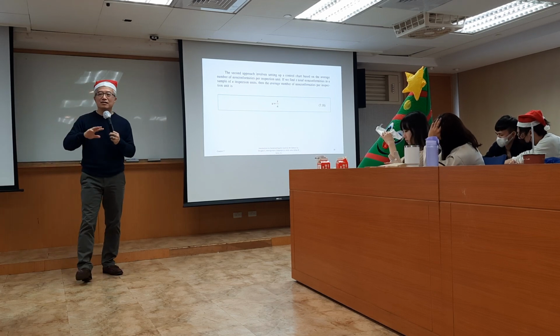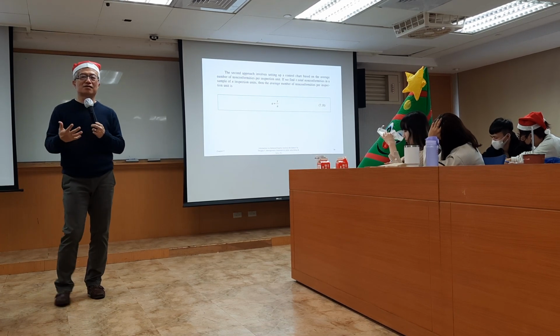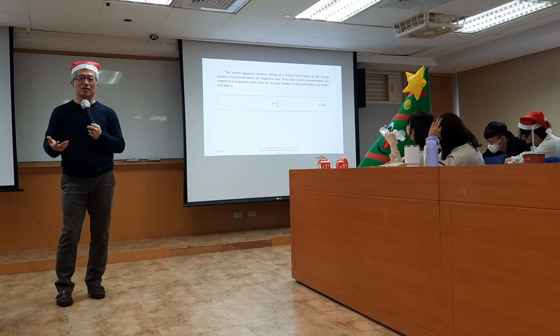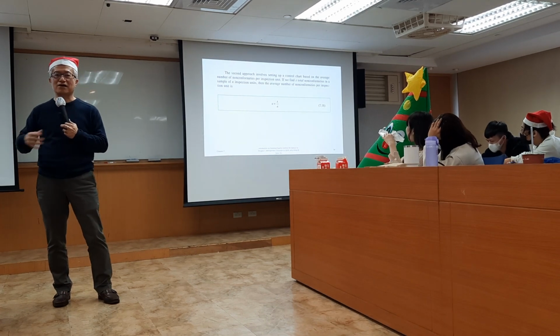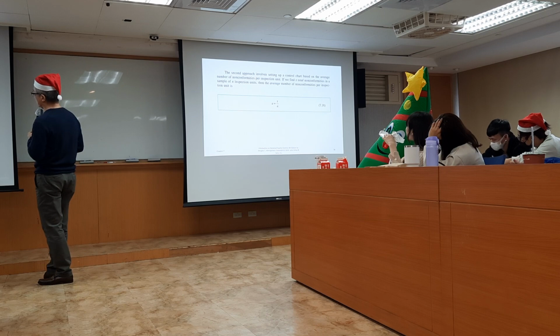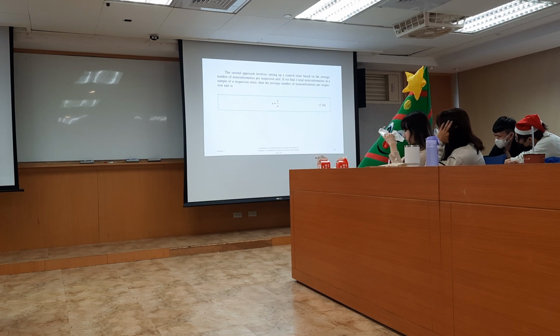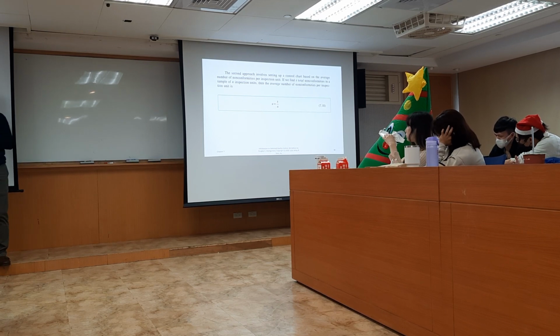And then we find X, the total non-conformities, divided by n inspection units. Sometimes n varies from time to time. This time we will take a sample of size 3. Next time we take a sample of size 5, and so on. Then the average number of non-conformities per inspection unit is X divided by n. This is defined as u. So this is called the average non-conformity control chart.